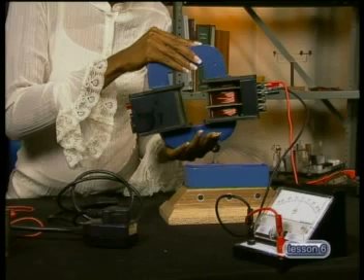Now have another look at the transformer apparatus. Notice the coils are connected by the laminated soft iron core. We know that soft iron is a magnetic material, which means that when it is placed in a magnetic field, it is magnetized by the field. However, when the iron is removed from the magnetic field, it is no longer magnetic. So in any transformer, the soft iron core links the magnetic field formed in one coil to the other coil. Any change in magnetic flux in one coil will be carried by the iron core to the other coil.